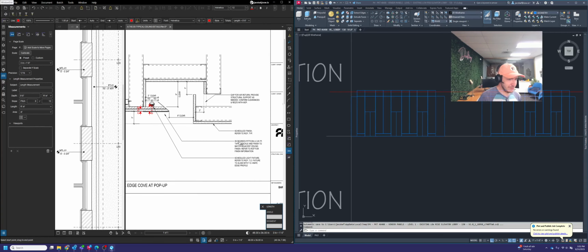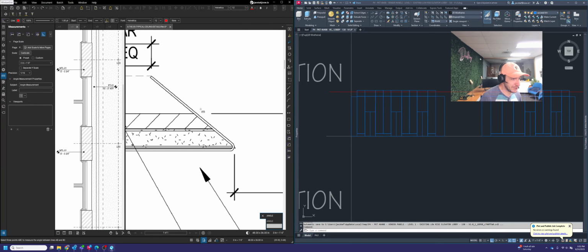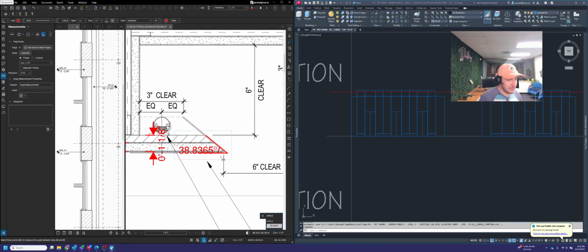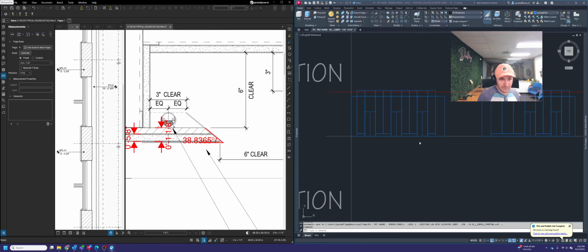They're calling that to be 39 degrees, which would mean that the angle... I could maybe pull the angular dimension on it here too, but it should be about 39 degrees. Sometimes it's hard to do the angular dimension in Bluebeam, but you can see that it's right about there. So that checks out. Okay, so let's start drawing this little corner detail in as best we can.